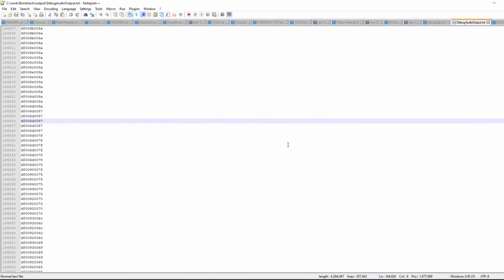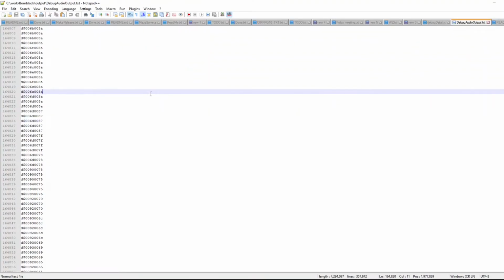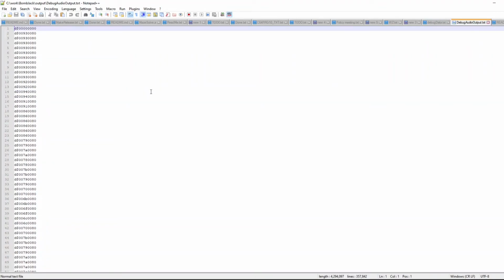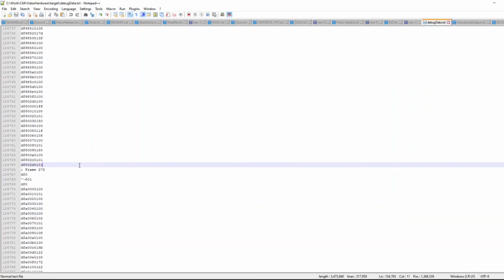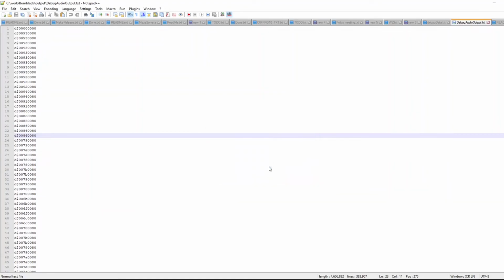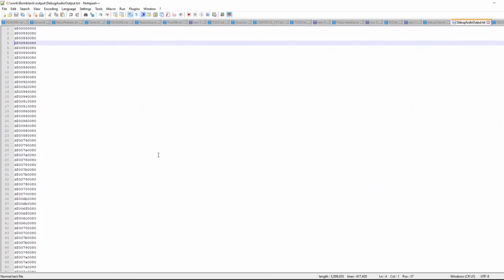of course, use this input file, save it somewhere, and use it as a golden source of data without having to generate it every single time from the emulated output. And that's what we do, we use this as a golden source input. Now, because the finite state machine simulation in the hardware is deterministic, we can use this golden source of input data, run it through the simulation, and compare it with an expected data output for what we expect,